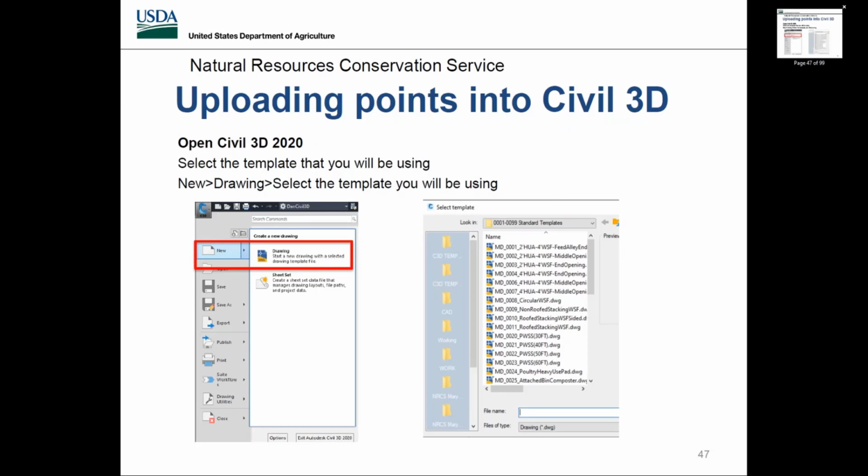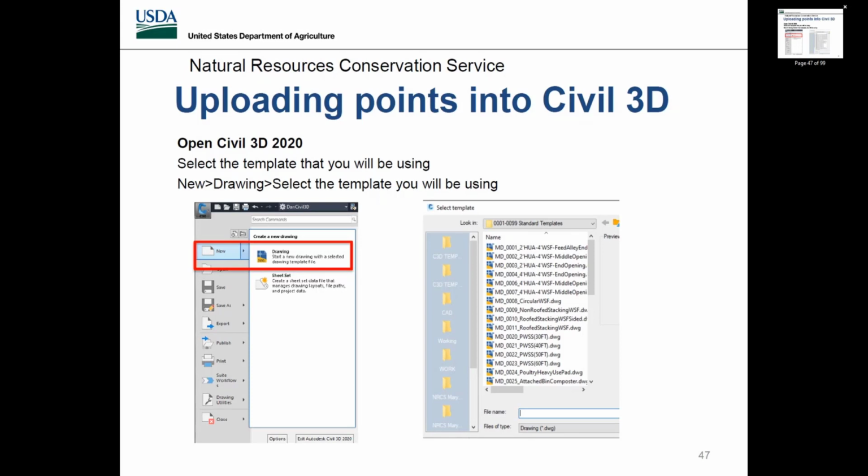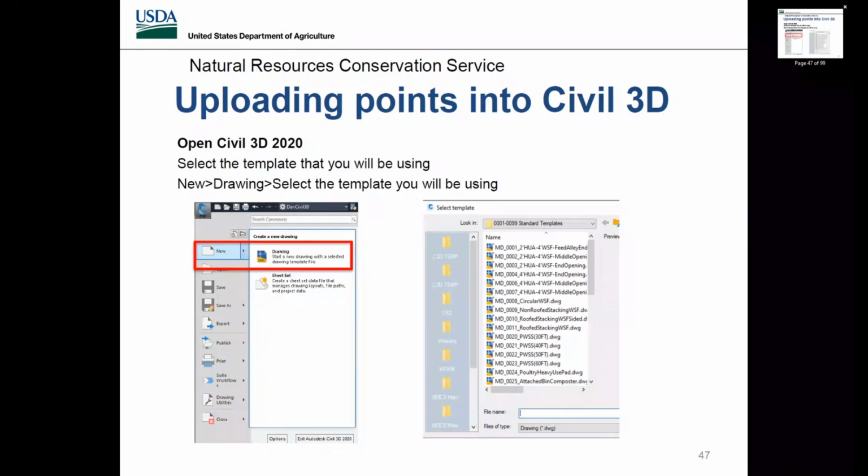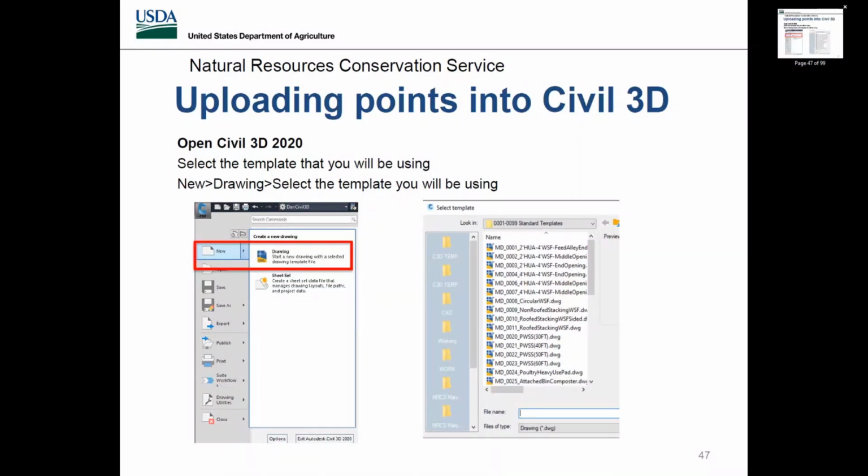Yeah, I know some of the older data collectors, it's a little tougher, but with the Magnet software, it's definitely much easier to use. The whole purpose behind the field codes really is to help. We're different than the private sector, obviously. In the private sector, you have a surveying group that actually goes out, does the surveying, and has specific field codes and field descriptions. When the designer uploads those points, the field descriptions draw all the lines in automatically, so the drafter has all that information there when they start drafting. They don't have to think about it because they haven't even been out to the site. We're a little bit different: we're actually going out doing the survey, bringing the points in, and drawing all the line work in.